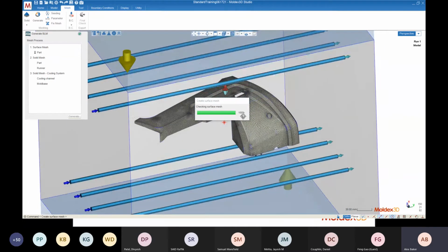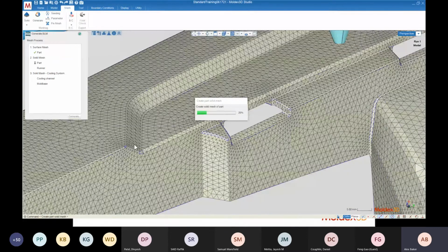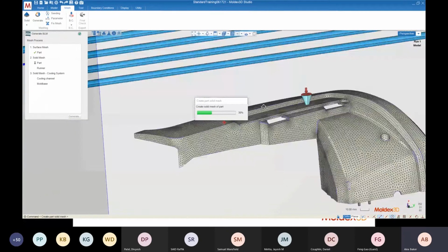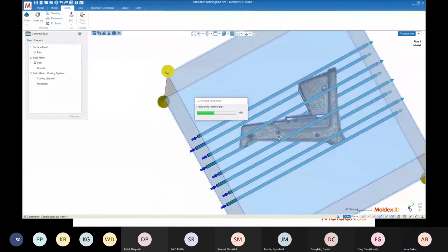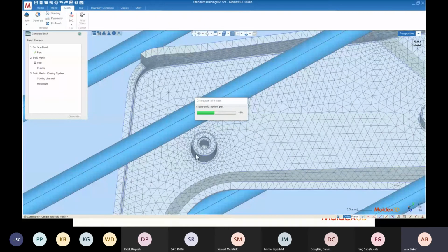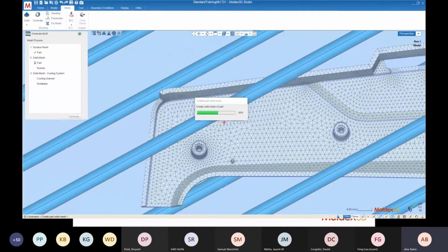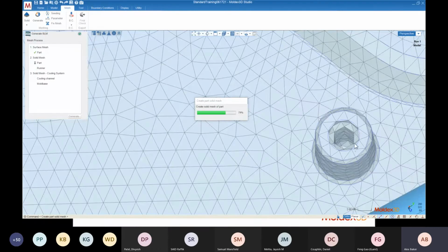And you can see that, just like I described earlier, the surface mesh of the part is literally just taking every surface on our geometry and converting it to a series of triangles. If we look at the bottom where we refined that boss and contrast those two, you can see that this boss is much better defined than this guy over here. You can see that hexagon that I was referring to earlier.